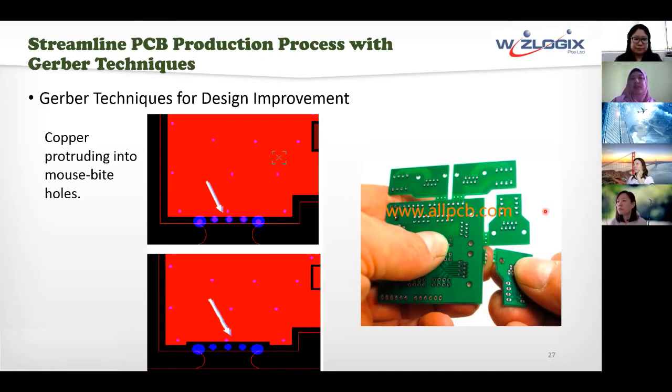So this is especially useful for boards that are smaller in size, and to increase your output or reduce costs, you can panel several designs together into one panel. So you can reduce costs as well as have the boards arrive to you, and you can break them off and use as required.